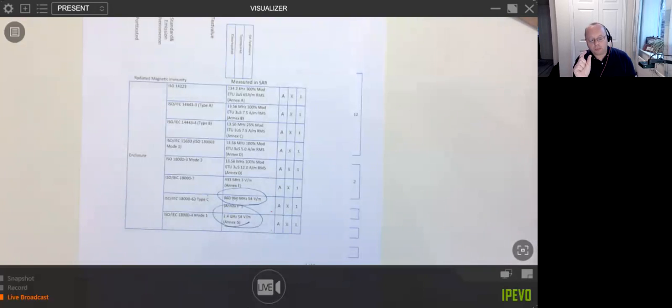And the smaller the boards are getting, you're starting to approach the wavelengths of some of those very high frequencies. So word of warning: battery operated products can cause you quite a problem at the very high frequencies. And trying to solve a problem at a very high frequency is certainly easier said than done.